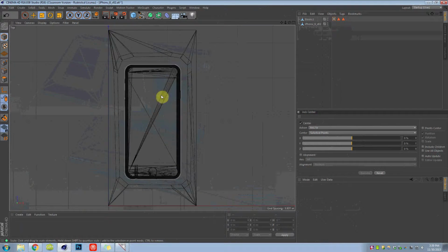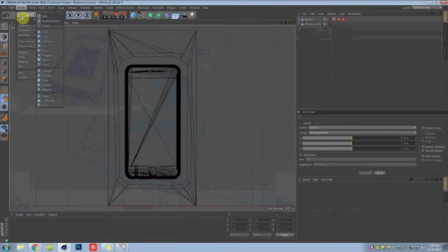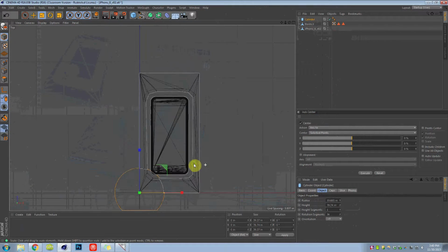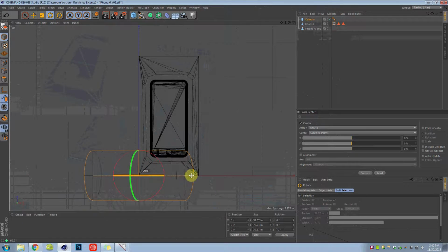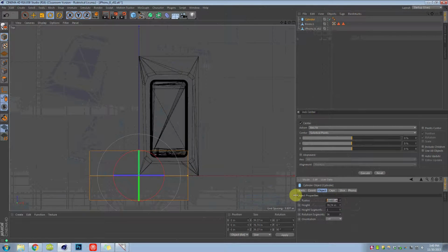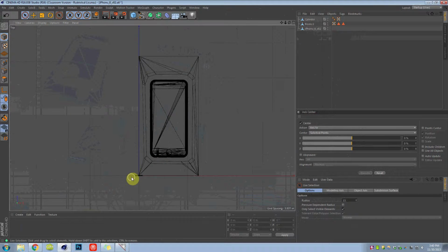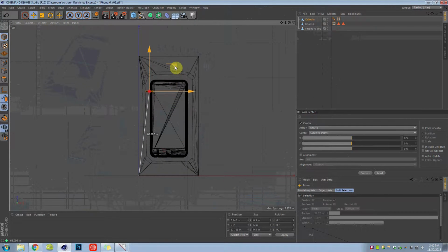Again, for this, I'm going to go to the top view. I'm going to create a cylinder, rotate it so it's facing sideways, and make its radius 0.25, so it's a 1/2 inch. Make this 6 inches. So now I have this little supporting structure that I can just drag and then duplicate wherever I want it to be connected.